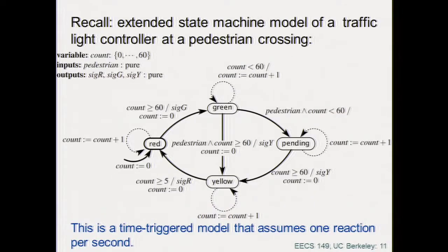Okay. Now, let's get back to our wonderful traffic light, and then the traffic light controller, we already said, is time triggered because there is a counter and the transitions are guarded by the value of the counter. Okay, so in this time trigger model, we assume that 1 to 60 means 1 minute, so every tick is 1 second. Now, notice immediately that the same mathematical characteristic of this model occurs when the unit of time can be hours, right, in principle. So there is an indexing in terms of a unit of measure that takes place, which is also a nice feature of these abstract models, that you can make them parameterized with respect to the variables that you want to set.